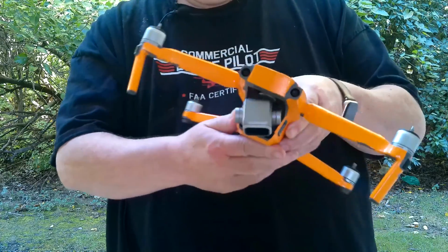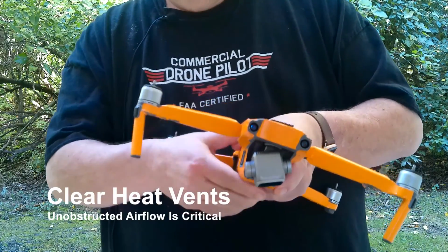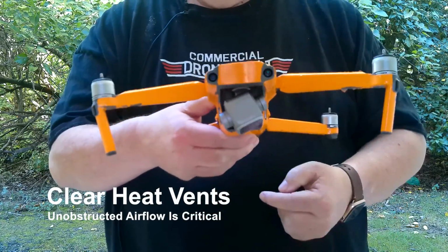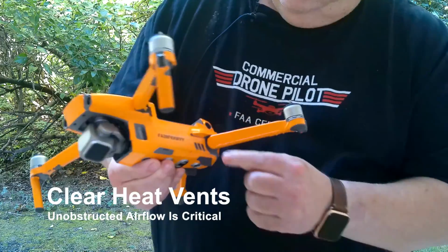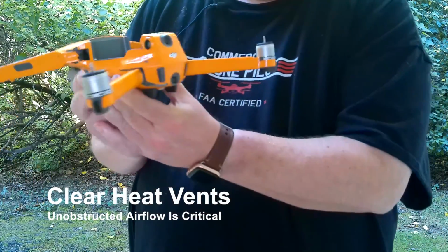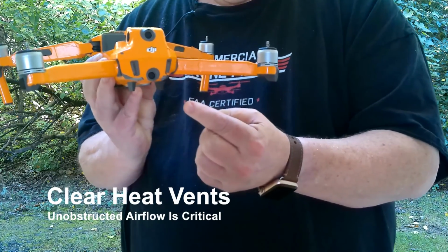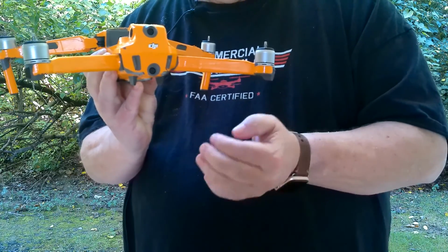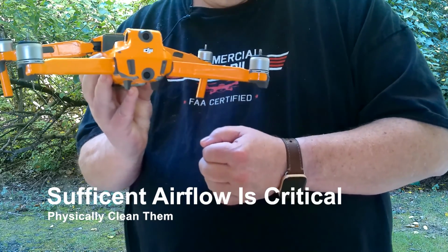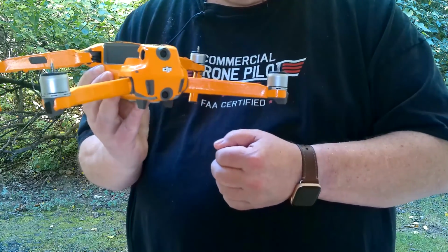You also want to inspect the heat vents. This particular drone has 2 vents forward, has vents on each side, and also has vents in the rear. These require consistent airflow so that your main circuit board remains cool and functioning in an optimal manner.